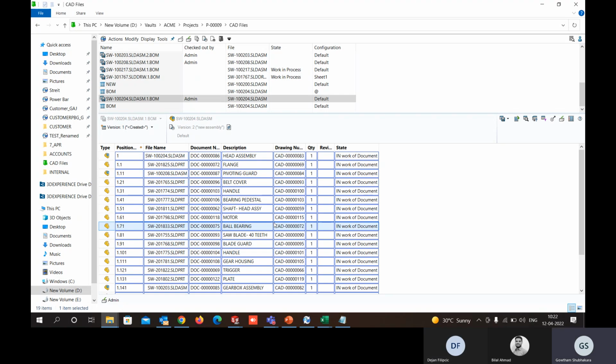From the PDM level, yes, we can directly export this as an XML format. The BOM, whatever we are creating, we can directly export to XML. We can trigger this functionality in the workflow itself, with no need of human intervention, so it will automatically generate. But from the Manage level, I need to confirm how we can link, because till now I never worked on this direct Manage DB connection with ERP. So I need to confirm this point on Manage.